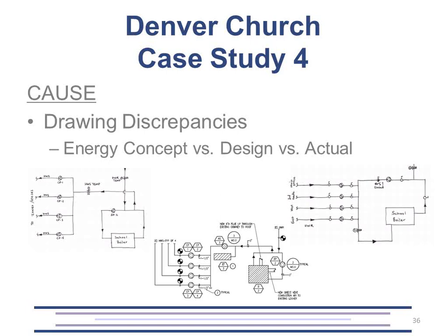It was a two-pipe system where the boiler and the chiller were being swapped based on chiller and refrigeration guidelines in small spaces, and so some of the piping had to be changed. In addition, because they were high-efficiency systems, condensing boilers, there needed to be more primary-secondary type piping, and a lot of that didn't happen. And this is just one of the examples of some of the drawings in part of this building.